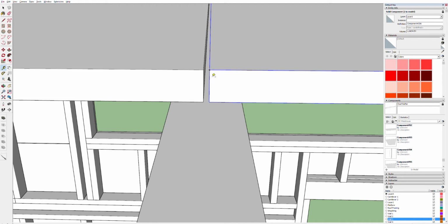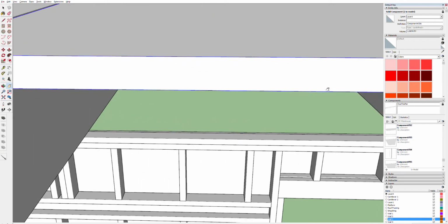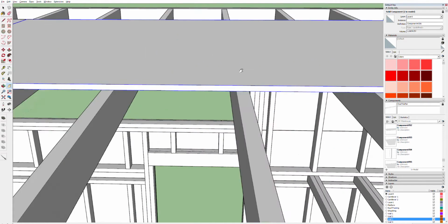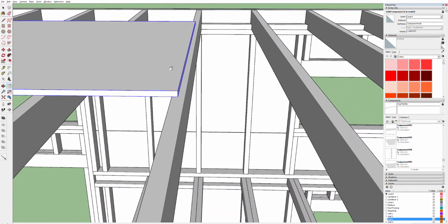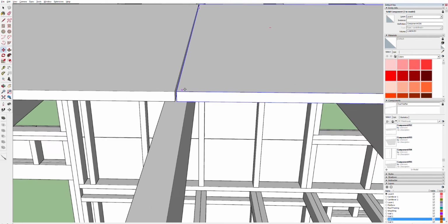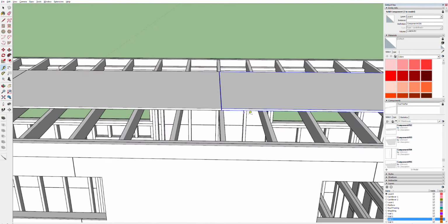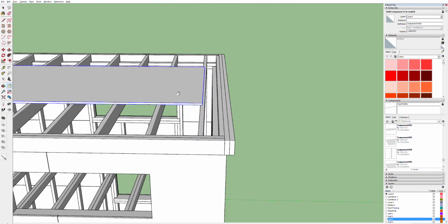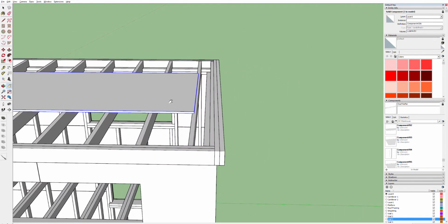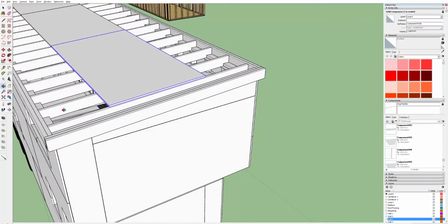So actually now I just need to move these 8 feet at a clip, and that'll get me right to where I need to be. Let me do that. Lock to green, copy, 8 feet even, should give me that 1/8 inch gap. Yep, okay. And I landed right there. Perfect.